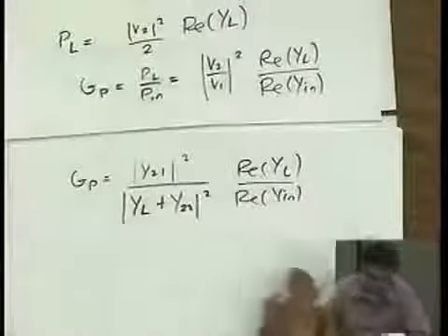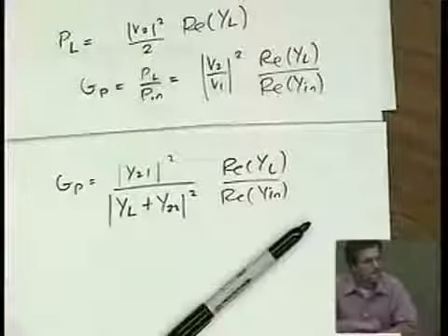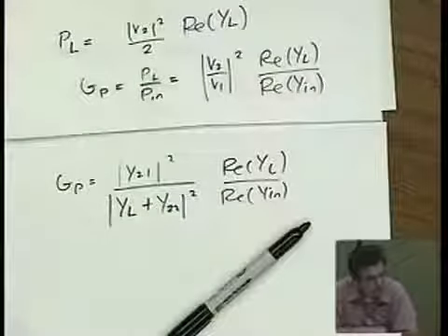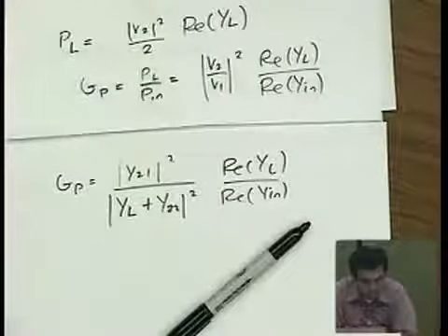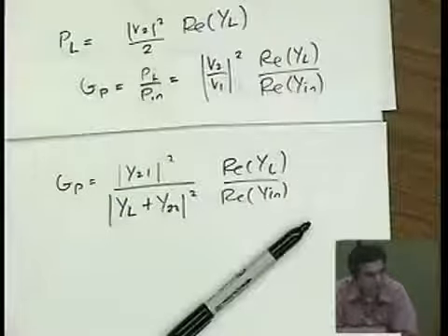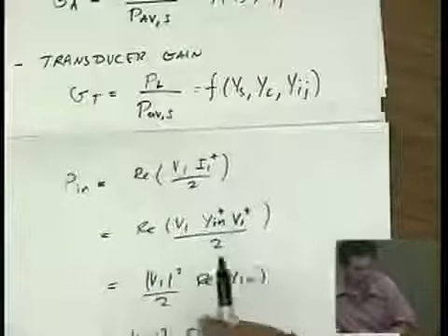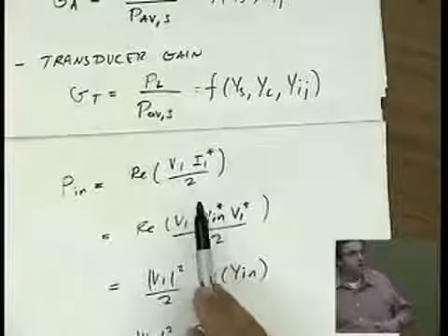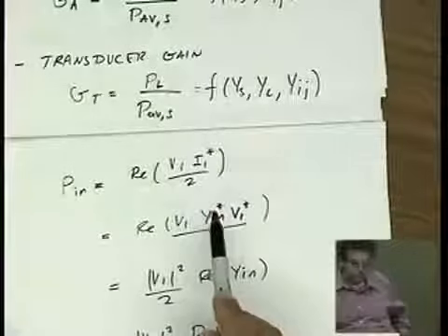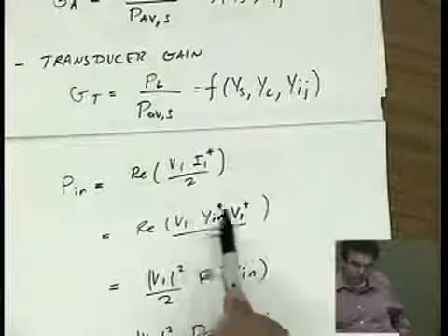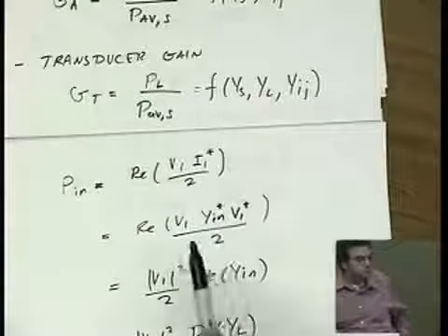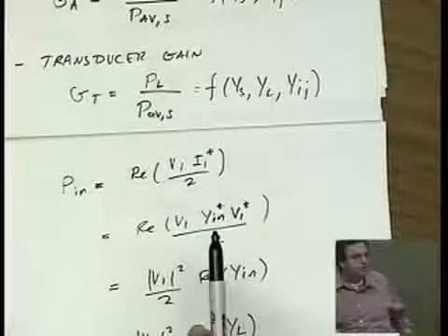Yes, question? Does this assume a matched load condition at the input when you are considering Pin? No, right? Because we just use a general expression for I1. I1 is the current going into a 2-port, determined by Yin. So we haven't assumed anything about matching.